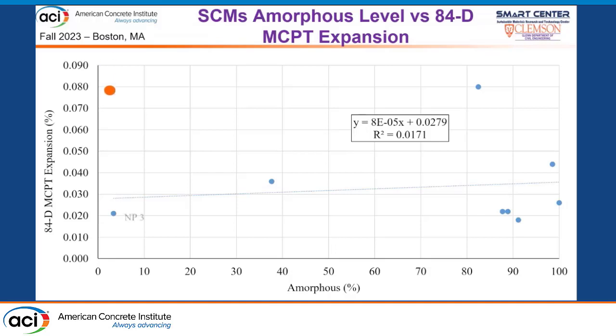Here, I want to point out the MP3 data point. Even though the amorphous level is very low for this material, it still shows very good ASR mitigation performance. So we predict that some crystal phase of the SCM can still engage in the chemical reaction. And here, the amorphous level was calculated based on the integrated surface area of the XRD pattern, using the integrated surface area of the crystal peaks against the total surface area.